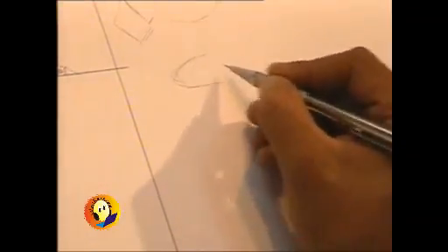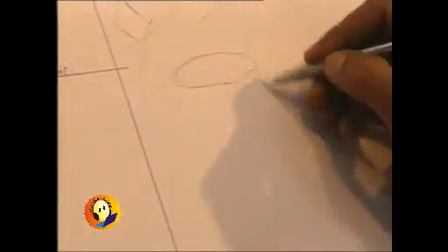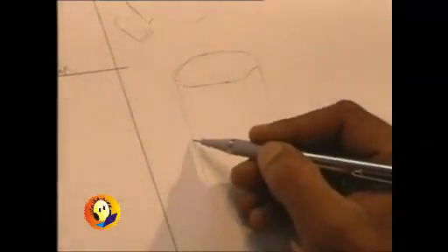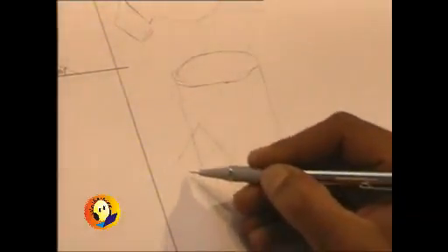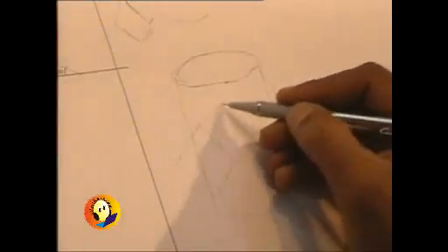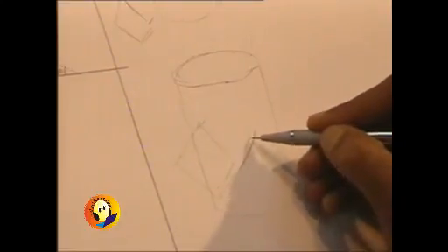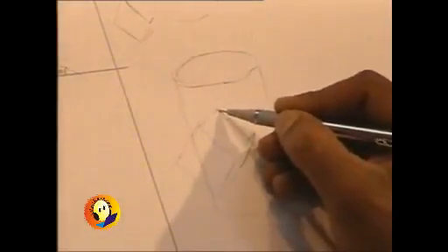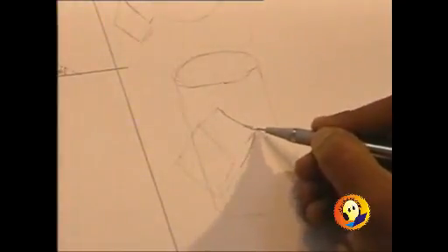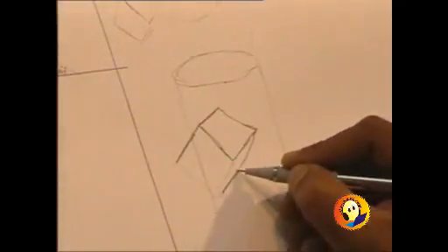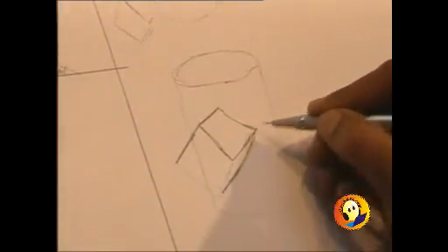Just imagine, this is a cylinder, and we have a square prism penetrating it. As it moves towards the circular portion, you will find that there will be a curve over here. There will be a curve which will be generated over here. This is how it is going to penetrate, because the surface is a curved one. So it is present fully till some point, then there will be a curve.